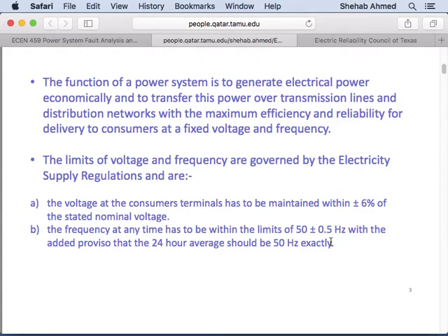Sure, if the speed changes, but why would the speed of the generator change? So typically, how does a generator work, right? You have a prime mover running the rotor. This rotor has the field winding on it, which you're supplying, and it's creating an electromagnet that has a certain orientation. But if you spin that, you're creating a time-varying magnetic field in the air gap. This time-varying magnetic field is linking the coils in the air gap and hence producing voltage at the terminals of the generator. Then you connect an electrical circuit.